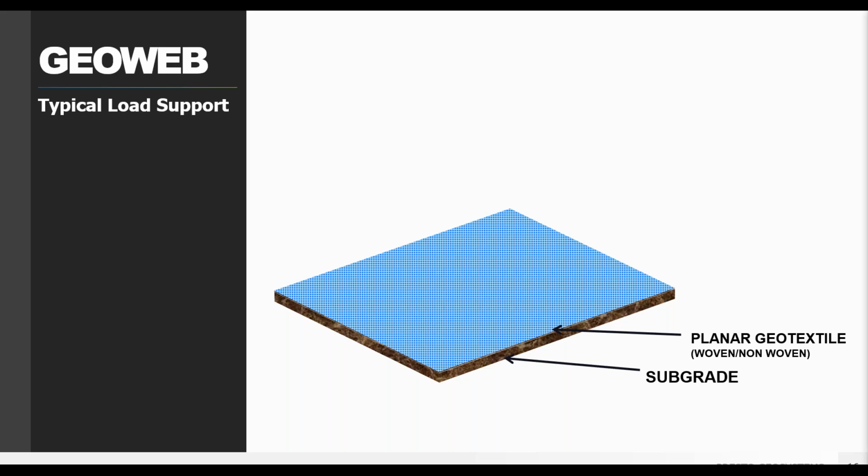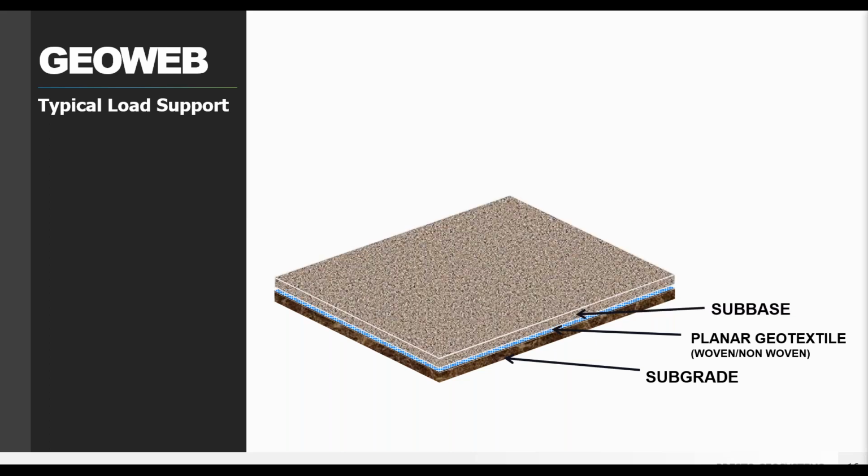This is going to be based on what your specific application is. Typically, if you are in perhaps a very wet environment or a very clay environment, having a geotextile there has some additional benefits. So then you potentially need a subbase of aggregate, usually. So it can be aggregate, it can be sand, it can be that salvaged, recycled material.